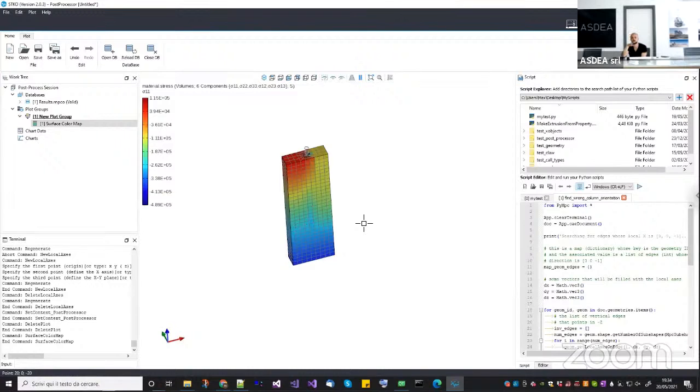So yes, if you use your own OpenSees MP on your high-performance computers, you will have to download the new source code and recompile it. Of course, because that element has been added to OpenSees. It's not just an STKO automation. It's actually in the OpenSees source code. It will be called zero-length implex contact, and I will show you in the next webinar how it can be used.